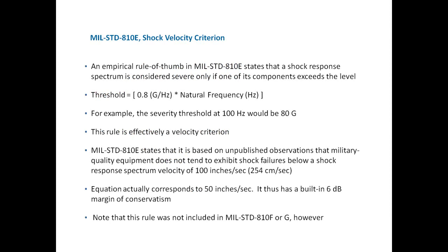We've talked about Mil Standard 810E before. Now, okay, I realize that Mil Standard 810 has been revised to Rev F and G, or I think H is in the works. But anyways, going back to Mil Standard 810E, there was an empirical rule of thumb stating that a shock response spectrum is considered severe only if one of its components exceeds the level, and here's the not-to-exceed threshold: 0.8 G per hertz times natural frequency in hertz.